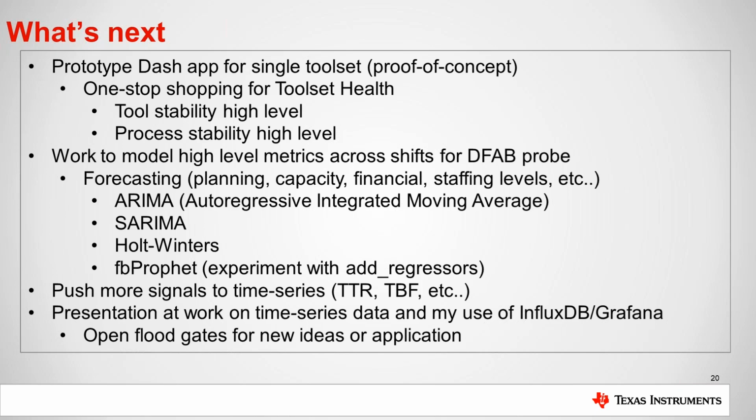Next question: ion implant versus diffusion is different, so how do you normalize both processes in time series data? Typically, so yes, they are different. One of them, you're delivering some dopant species through an E field and bending it with some B fields to implant it. The other, yes, we're attacking pretty much the whole substrate with, say, a phosphorus.